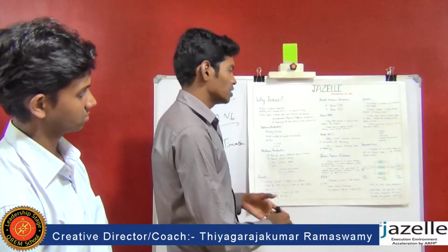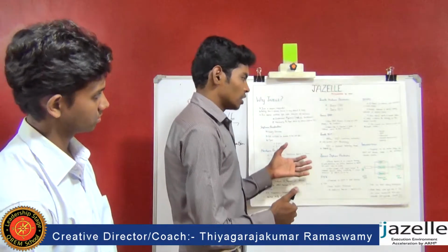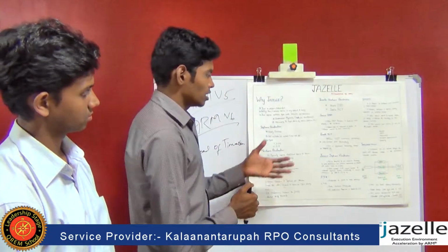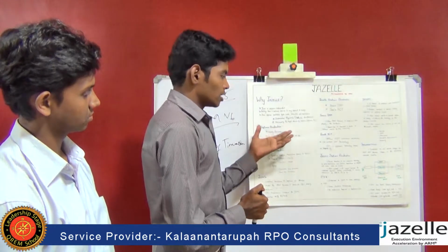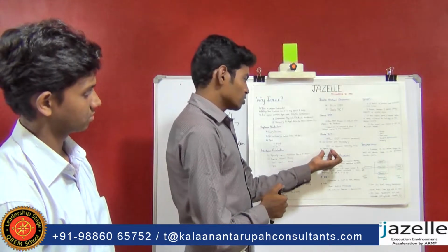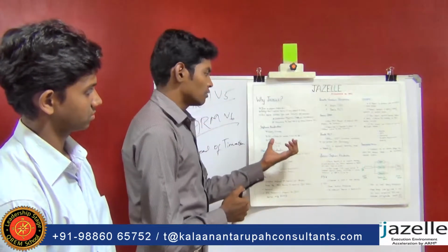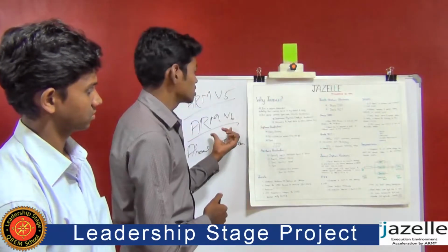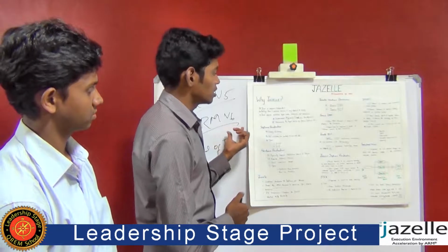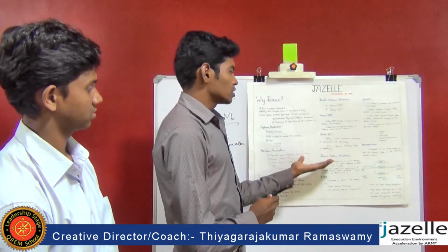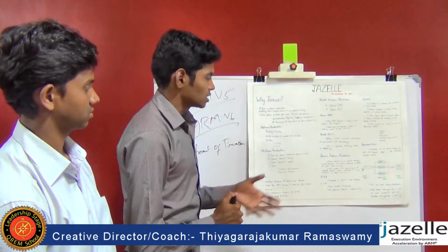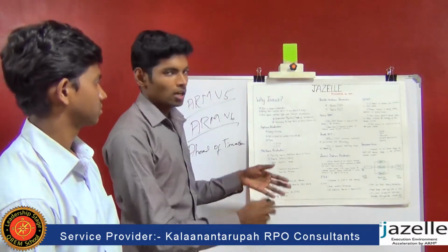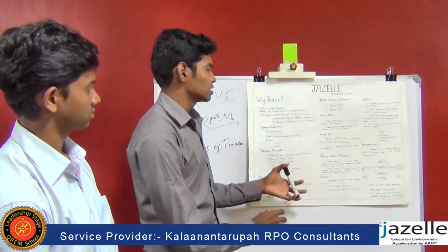It is different from the... it is based on the Thumb EE. Thumb EE is an execution environment which is used in the ARM v6 for Jazelle technology. There are many features added in the Jazelle RCT, such as array-based check and null pointer check. These are the main features added in the Jazelle RCT.